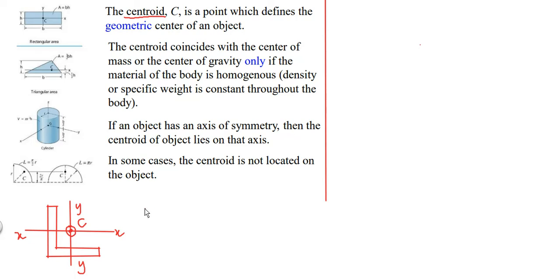And if we have something like a steel channel, it looks something like this. I'll draw it roughly. I'll draw its axes. There's the x axis. The y axis will be sitting somewhere over like so. And where the two axes intersect each other, that is the centroidal position for the channel. So there are some sections which have their position of centroid sitting outside of them, but generally most centroids sit inside of the body.